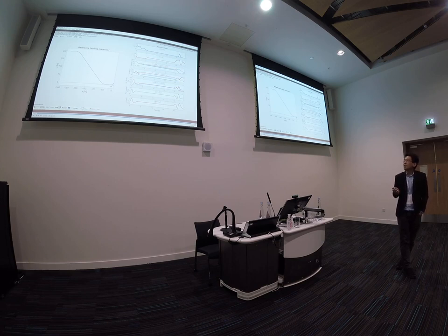At the end, for perching, let's see. To perch, the airplane increases the thrust here to escape deep stall. Now, what happens next? You have more lift after you escape the stall. And then for perching, you increase delta E. Increase angle of attack here, increase drag here, and you lose the lift. That's what happened.